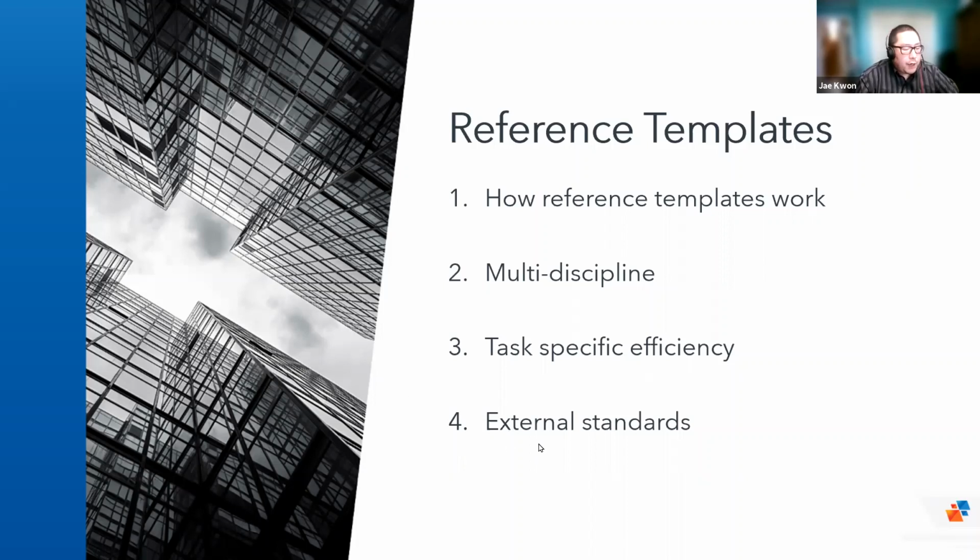And finally, external standards. Maybe you need to prepare drawings using a particular template for a client, like their own template. You may want to reference that into your own drawing or your own template and have it override a bunch of styles, so that it's a lot easier to transfer the files over when you're done your design. Or maybe you receive drawings from your sub-consultants and you like to reference your own standards into their drawing and then continue working on them.